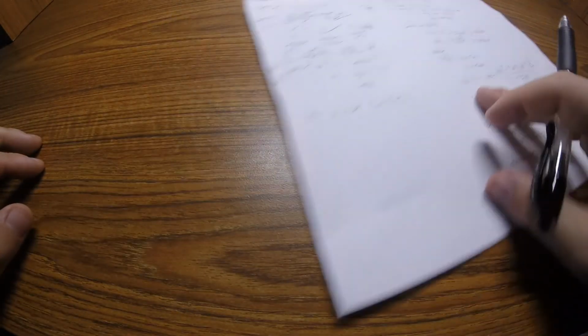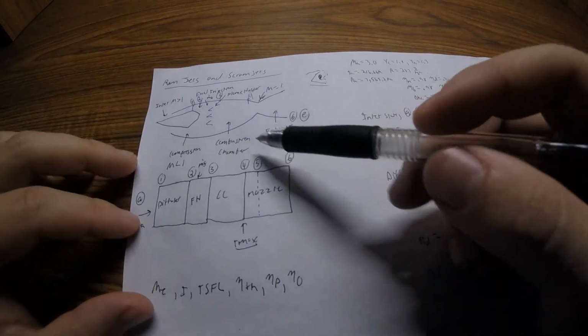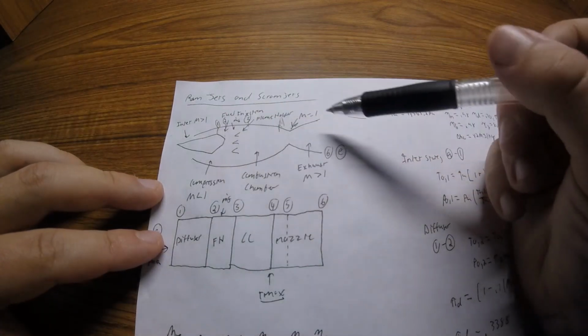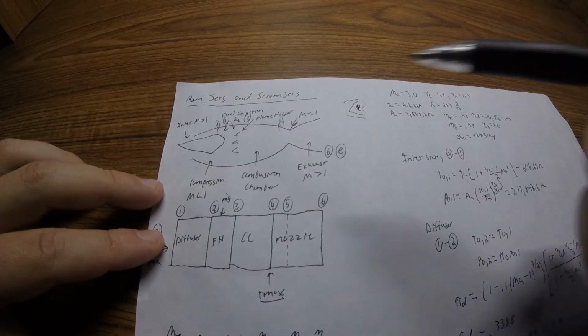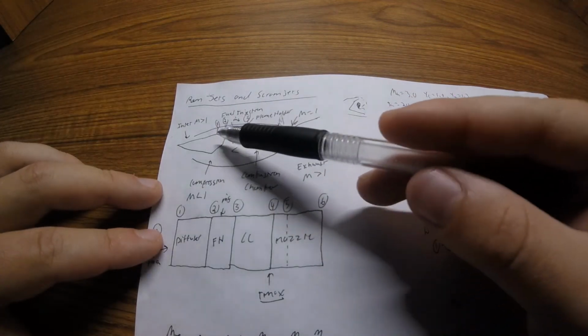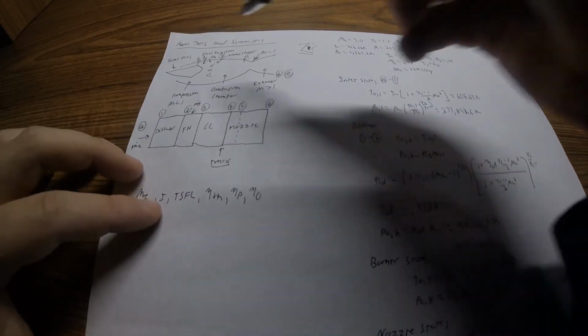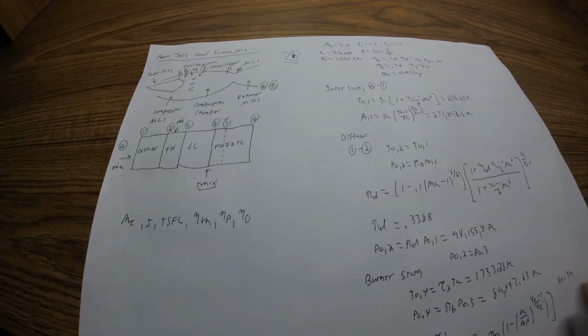The last thing I want to say, I don't know if I mentioned this earlier, is that the efficiency of a ramjet decreases at really fast speeds, because the temperature difference between the inlet states and the outlet states decreases. So you can't extract as much thrust or energy when the difference in pressures or temperatures isn't larger. You want a large difference in temperatures. So there you go. We calculated temperatures and pressures at all the states, calculated a bunch of good values to know to compare different engine specifications, and we learned what a ramjet is.